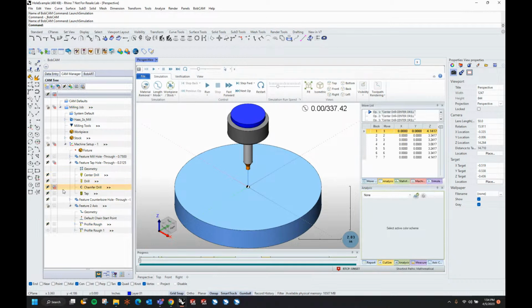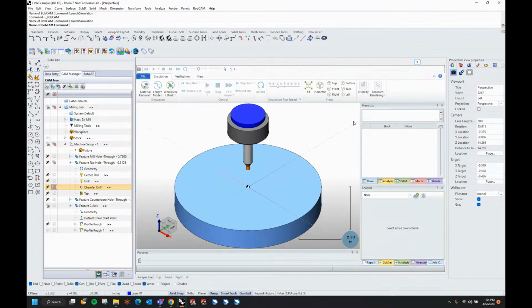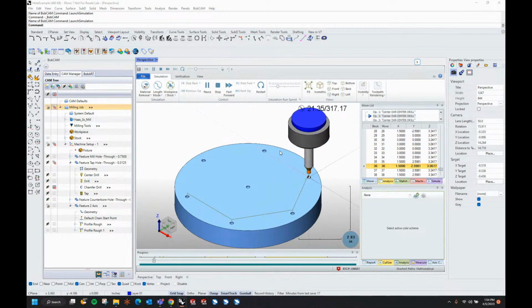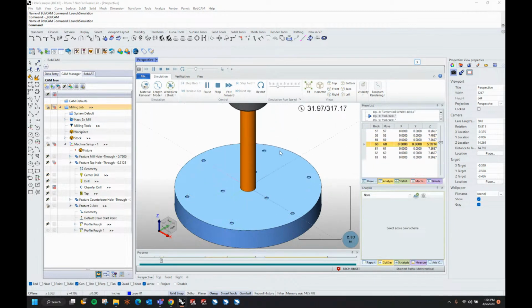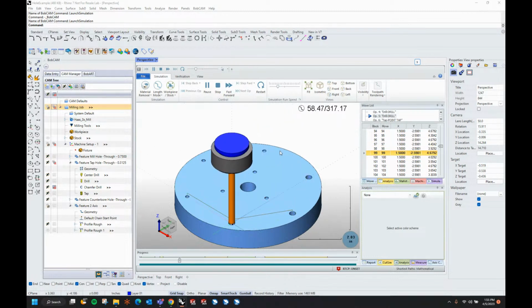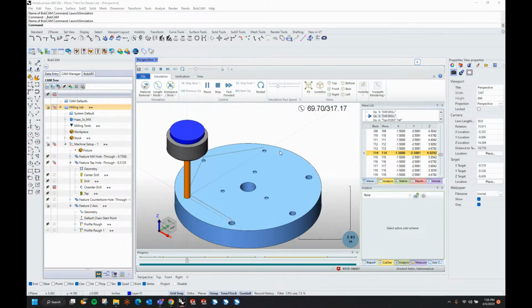Now I want to disable that chamfer drill. So if I just hit the post yes, no here and hit start simulation again, it'll actually get rid of it, and we won't even see that operation happen in the simulation at all. And it's all right, the open pocket didn't work on this one. We are going to look at an open pocket on the next part. So that's fine. That works on the outside at least. That's where most of the open pockets are. A lot of open pocketing you can get away with doing the side roughing on profile if it's an internal one, but definitely should have that looked at to see why it's not working.